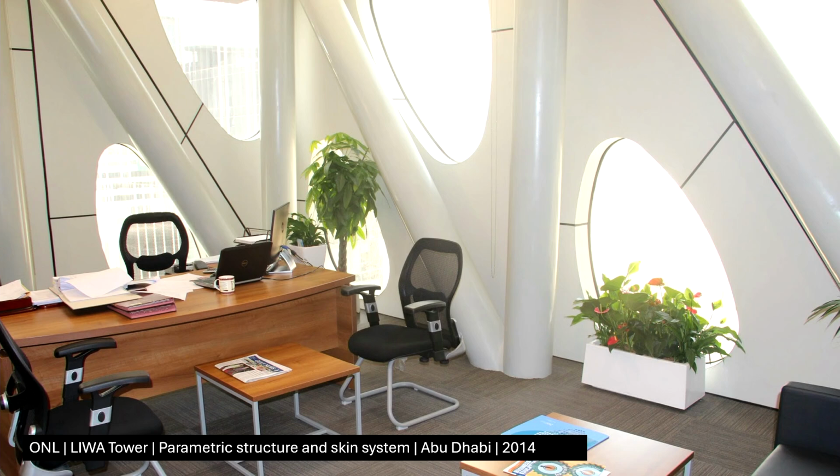because it's triangulated. So here we have the benefit of triangulation, which is also beneficial to the other projects. A triangulated structure is a network. It's stable. If you take out one of those, nothing happens. The forces would go around and find their way. If you have a structure with columns and beams, you take out one column, well, you know what happens.